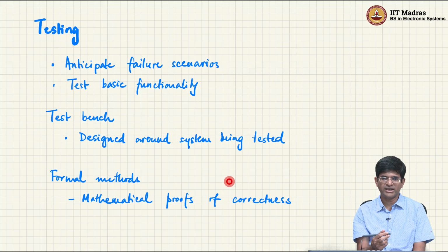I probably need to test for a few corner cases, switching from up to down, switching from enabled to not enabled. What happens if I enable while the load is on, if I disable while the load is on, right? All those a few different combinations of that sort, and yeah, I'm good to go, because I don't really expect a threshold of 10 and a threshold of 20 to really make a difference in terms of how the system behaves, right? And that's reasonable. That is what is done in practice, right?